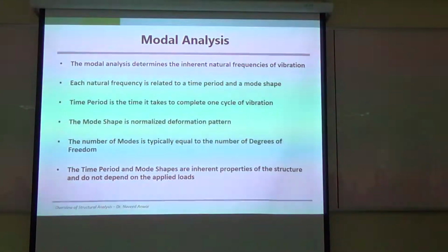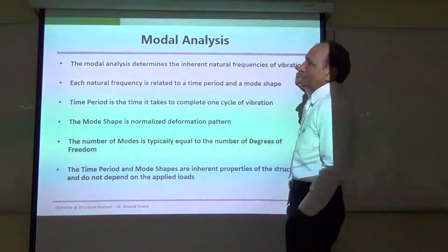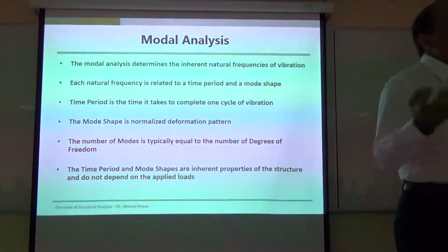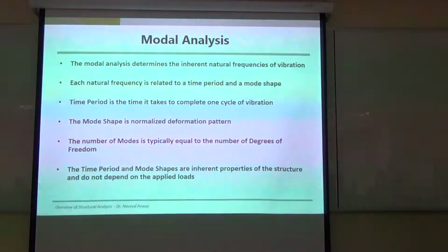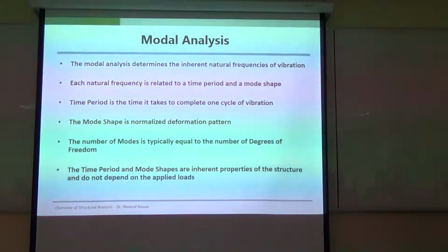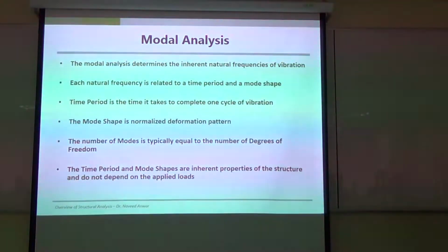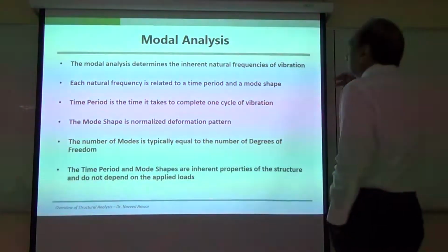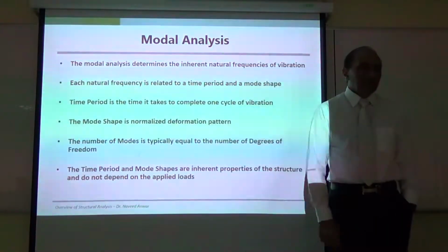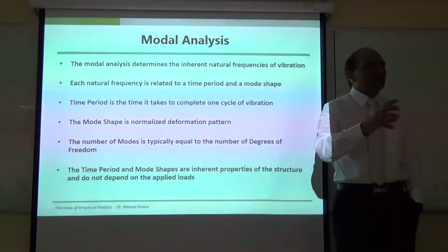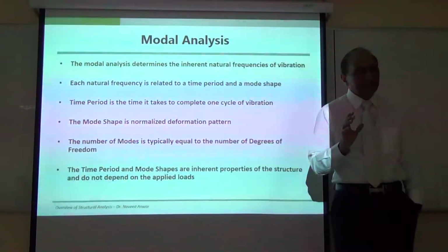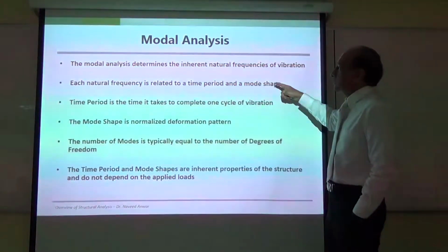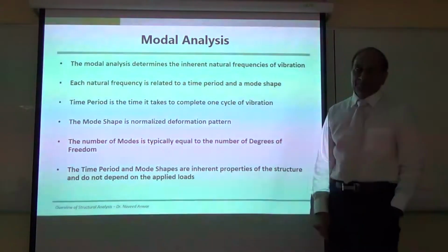So the modal dynamic response. The modal analysis determines the inherent natural frequencies of vibration. This is the property of a structure. Does not depend on load. Just like moment curvature, just like capacity that we determined last time, they are properties of the cross section, do not depend on the load. Same is the case. Natural frequencies generally do not depend on the load. They depend on the stress state, they depend on the stiffness at any given time and the mass. That's it. Nothing else. Each natural frequency is related to a time period and a mode shape.